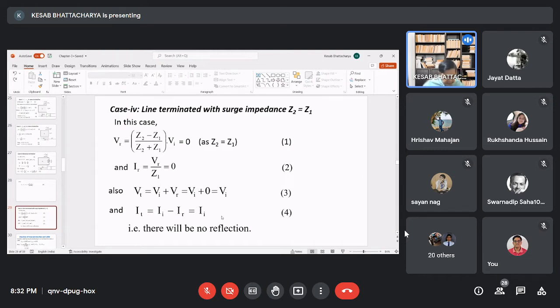The waveform of both of these two have to be recorded, and that recording is done on the computer screen. Therefore, from the transformer and also from the impulse generator end, two signals are to be taken to the input of the computer.